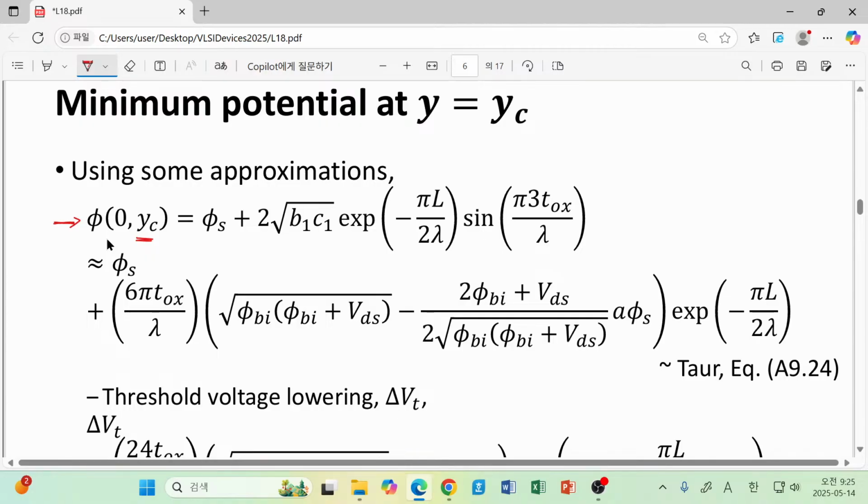This value is interpreted as the minimum surface potential, and we will treat it as the corresponding value to the maximum EC value seen from our electrons. So that is the maximum height of our channel energy barrier. So that is quite important.